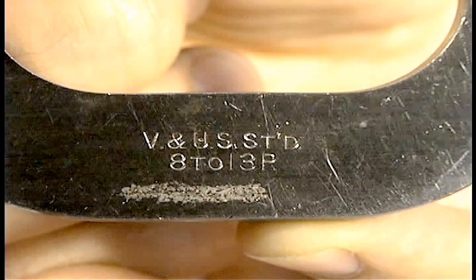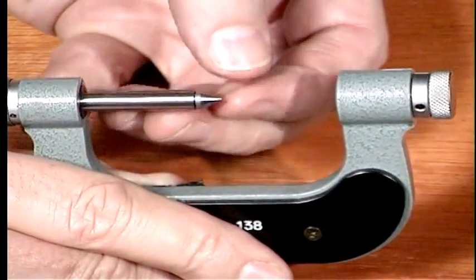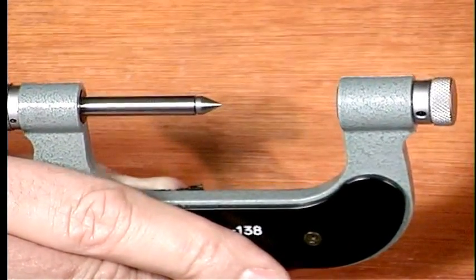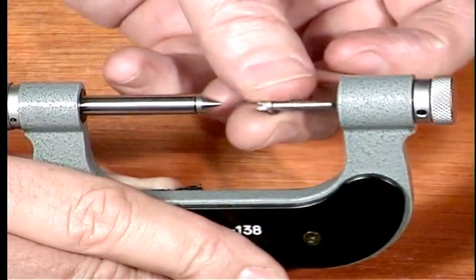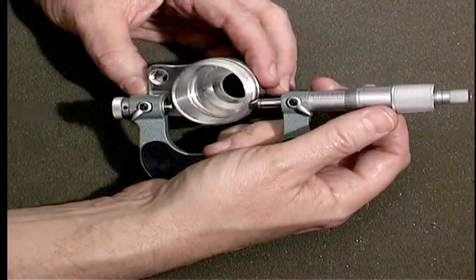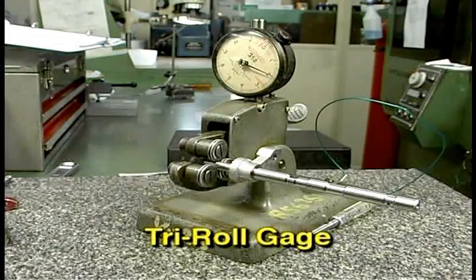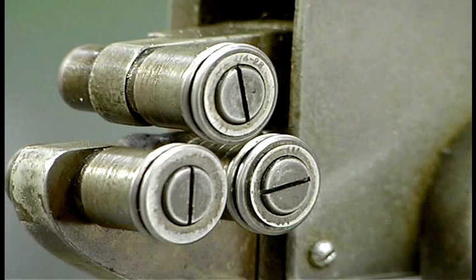Check the markings on the pitch mic to be sure it can read the thread size. Some pitch mics have replaceable spindles and anvils to match the thread pitch being measured. Install the correctly matched set. The pitch micrometer is read just like other micrometers. A tri-roll pitch gauge can also be used to measure the pitch diameter of OD threaded workpieces. The tri-roll pitch gauge has 3 threaded rollers which engage the threads on the workpiece.